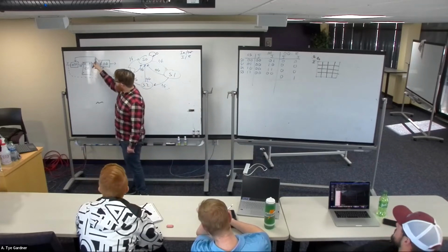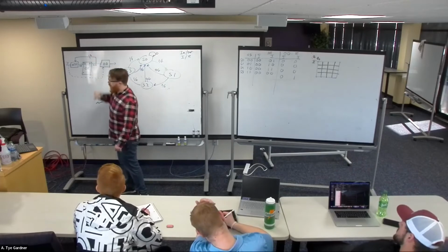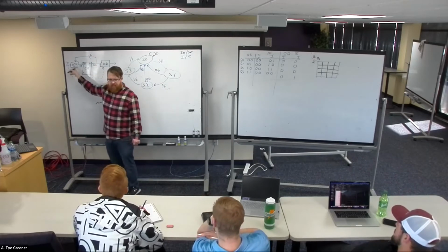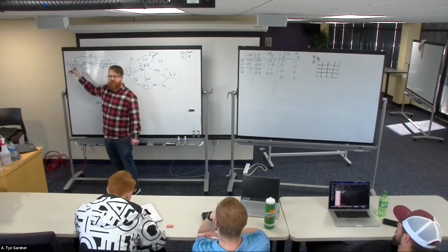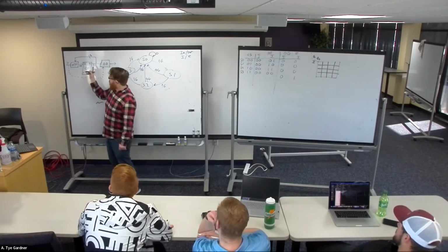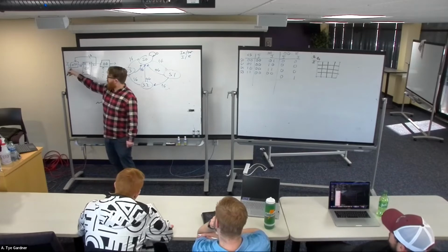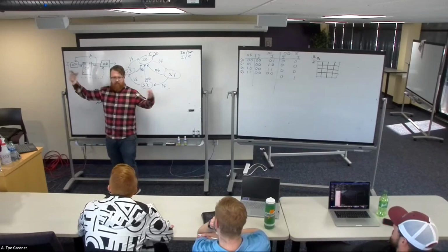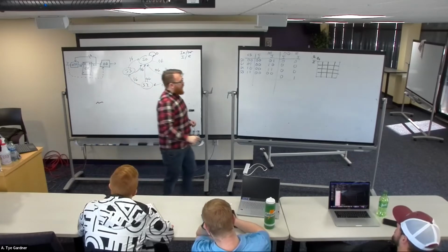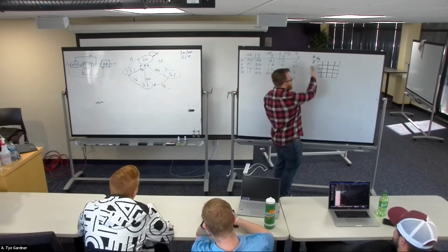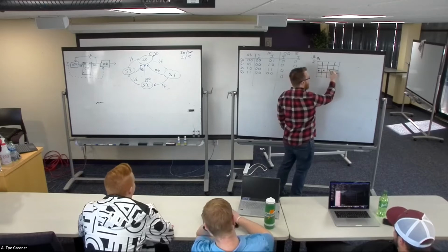This signal that is 2 bits wide that's coming back into the next state decoder, that's what we're building, right? We're building combinational logic to go in here that looks at the 2 bits in the current state, the 1 bit of the input, and says what's next, right? That's what we're building. That means, because I haven't assigned here, there are implied don't cares down here.